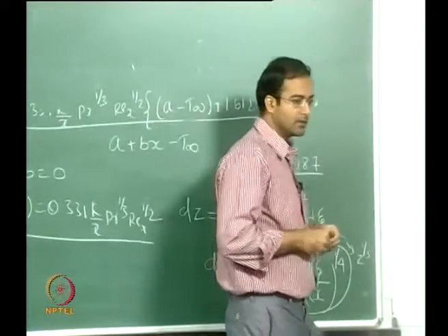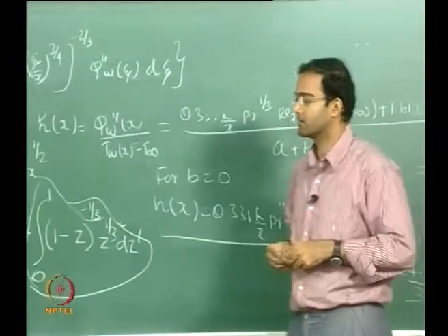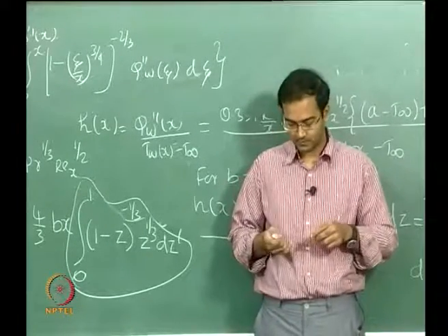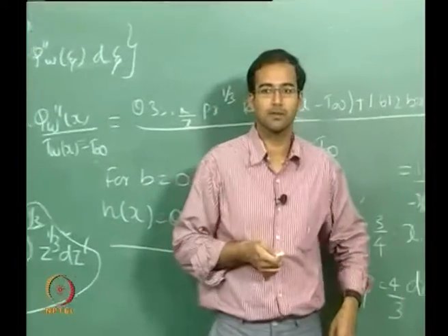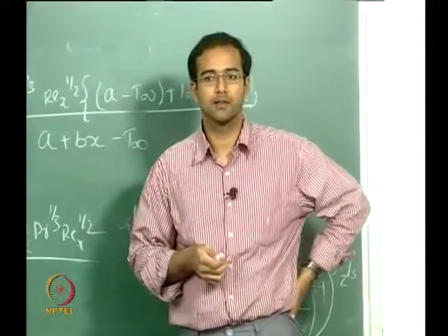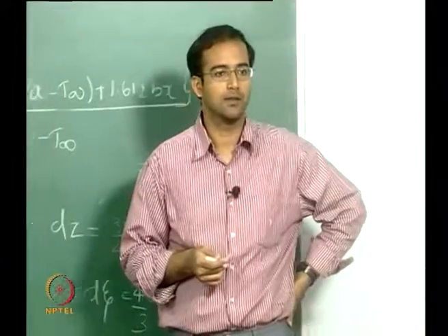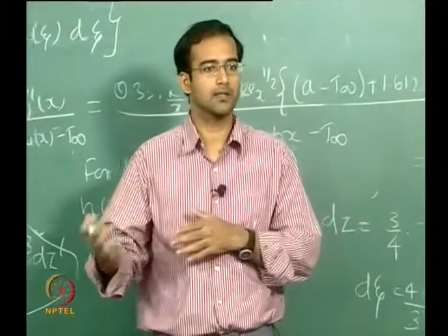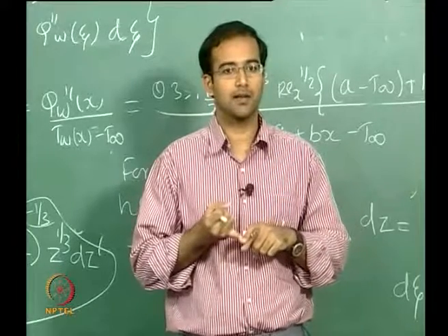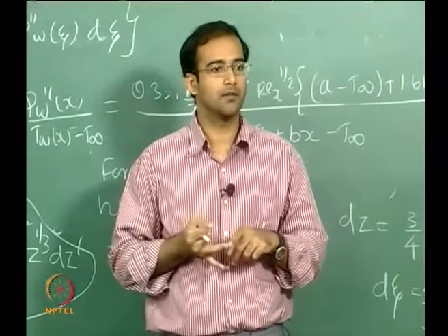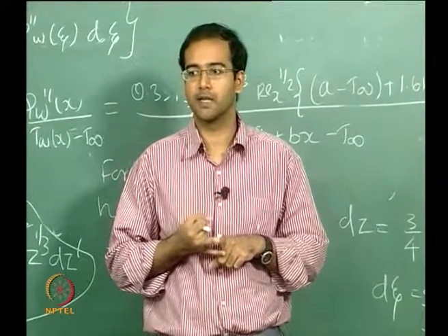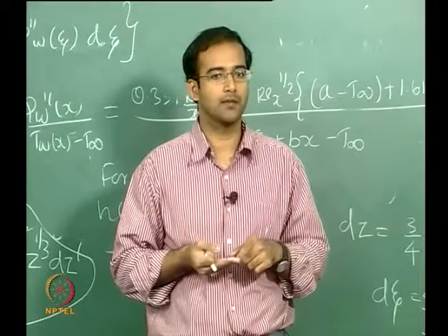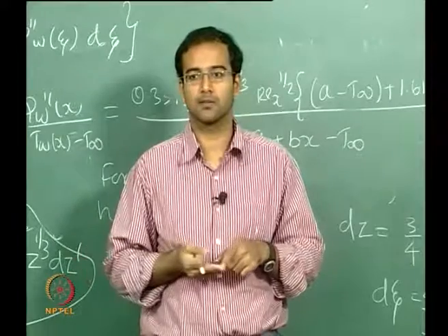So I think with that we will wrap up the external laminar boundary layer flows. We have covered quite a bit. We have almost covered whatever similarity solutions are possible under external boundary layers, and also the approximate methods. Whatever external laminar similarity solutions there are, they have complementary integral solutions also. Like we have seen, if you have the Falkner-Skan solutions for the wedge problem, you have a similar von Karman-Pohlhausen solution when you use the integral methods. Of course, like the Blasius solution, there you can approximate some velocity profile and very easily find the expression for, say, the local Nusselt number.